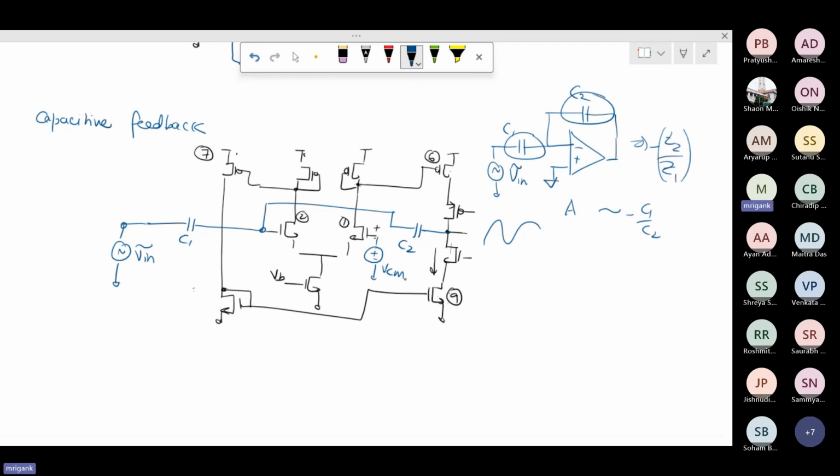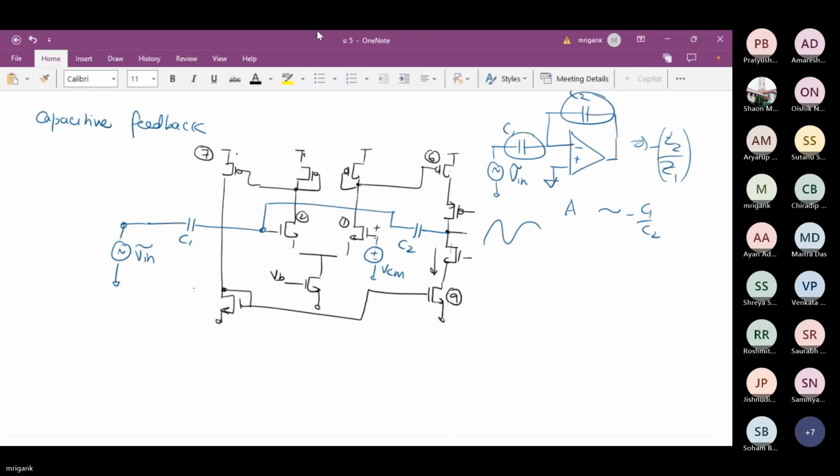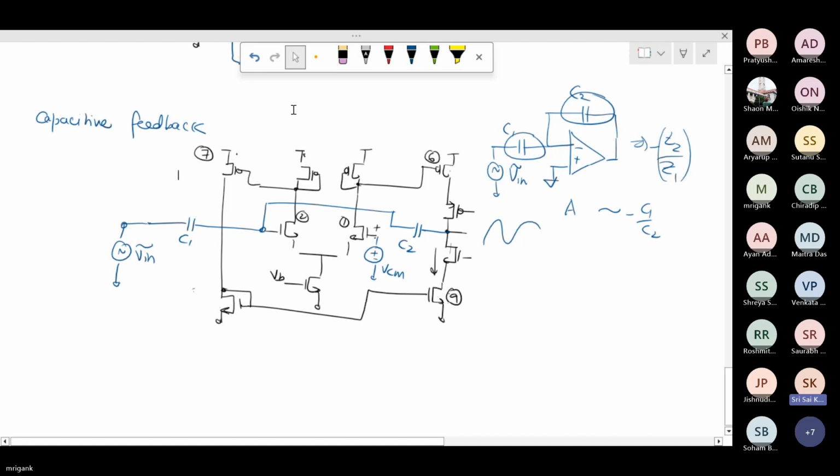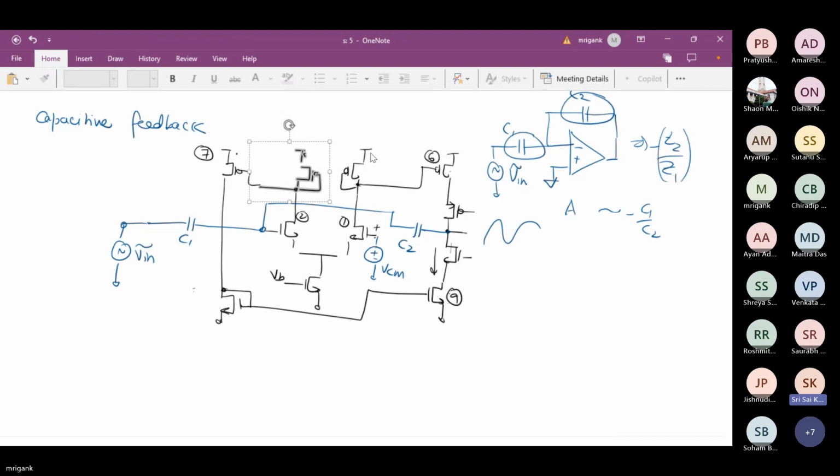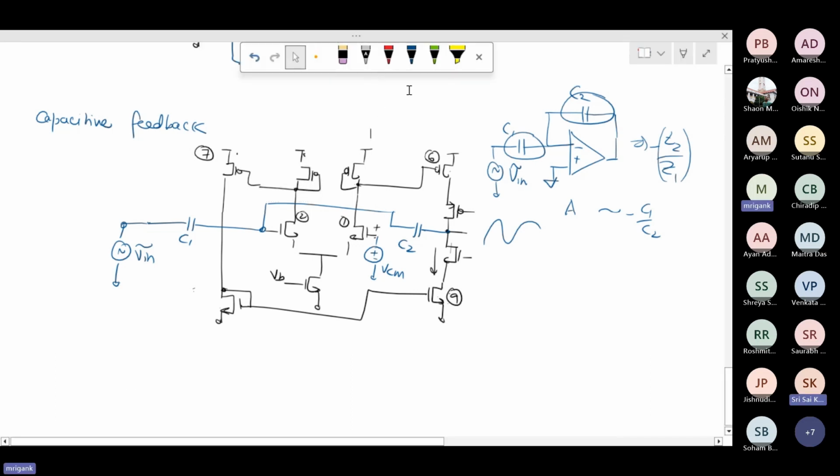Any response to this? You don't see any problem in the circuit? Sir, when we were learning op-amps, we were taught that the output resistance of an op-amp is nearly zero or negligible. But in this output configuration, the output resistance isn't negligible, right, sir? So that's why we need a buffering stage to make it zero.